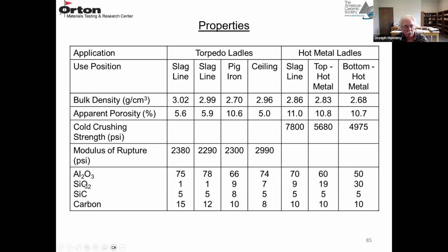That has really low thermal expansion. So this is added to provide thermal shock resistance. So it's only 1% here, 9 and 7. And then these go quite a bit higher, all the way from about 9 to 30% fused silica. So the fused silica is an addition to improve the thermal shock resistance.